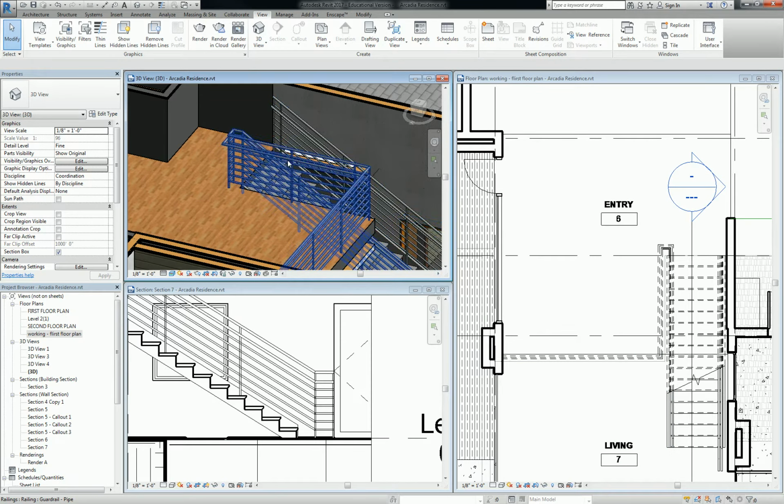Any questions? Yes? Does it change the height of the top rail when you do that? Because when the top handrail was drawn originally, it met the front tread of the second floor, or the front face of the second floor. But then when you drew that next line segment, that placed, I don't know, whatever the height it was, 36 inches at that floor.